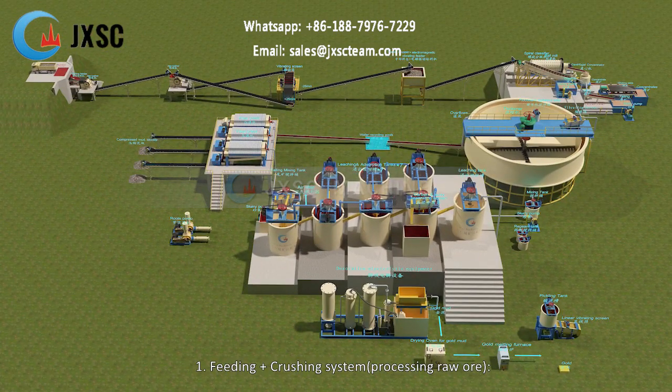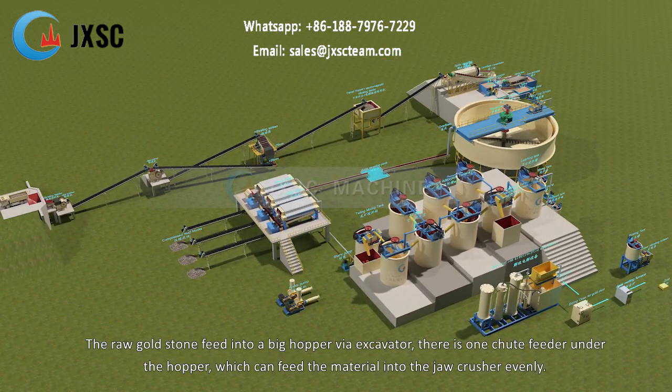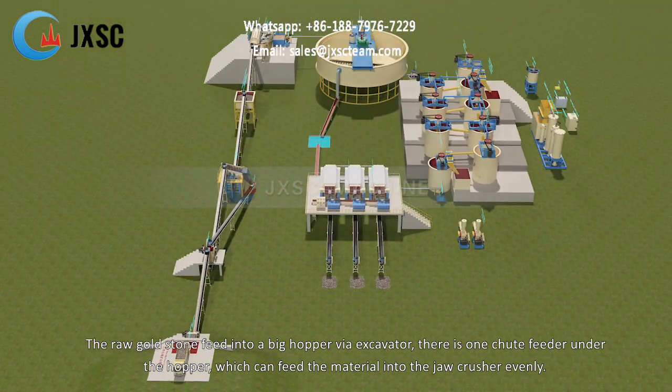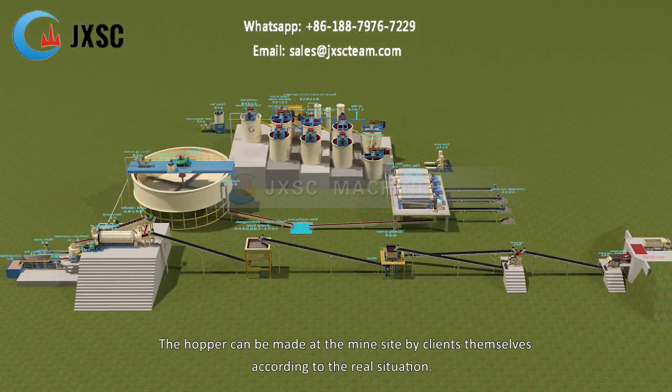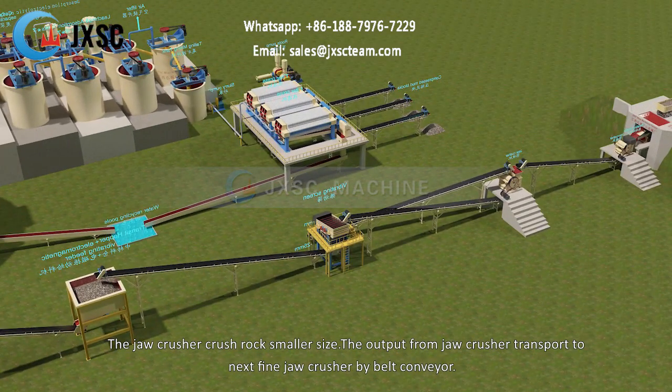1. Feeding plus crushing system, processing raw ore. The raw gold stone is fed into a big hopper via excavator. There is one chute feeder under the hopper, which can feed the material into the jaw crusher evenly. The hopper can be made at the mine site by clients themselves according to the real situation. The jaw crusher crushes rock to a smaller size.